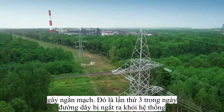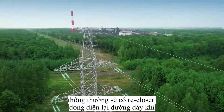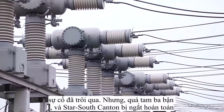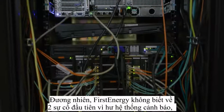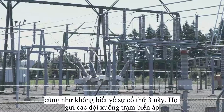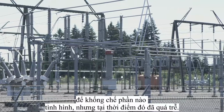It was actually the 3rd time that day the line had tripped, but it was equipped with circuit breakers called reclosers that would energize the line automatically if the fault had cleared. But the 3rd time was the charm, and the Star South Canton line tripped and locked out. Of course, First Energy didn't know about the first 2 trips because they didn't see an alarm, and they didn't know about this one either. They had started sending crews out to substations to get boots on the ground and try to get a handle on the situation, but at that point, it was too late.